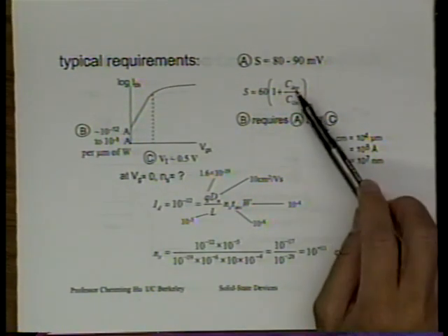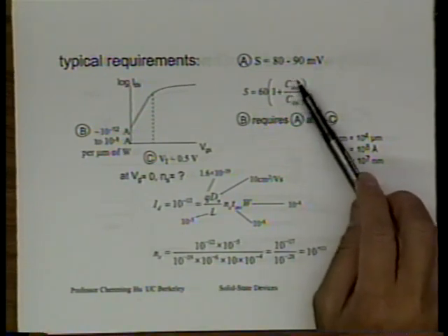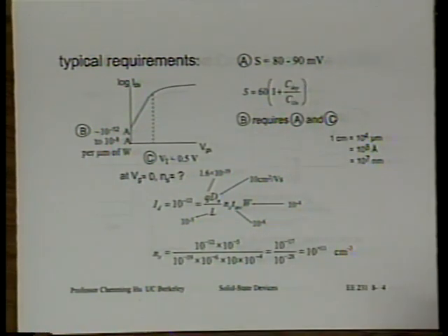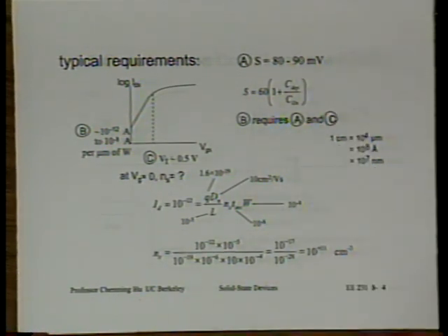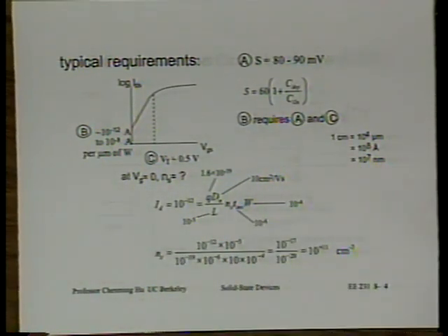The reason is we also have been reducing the depletion region thickness, WD max. One reason, which we mentioned last time, is to control the short channel effect. We have to use small WD max. So we're not really getting better swing either. So that pretty much maintained this value. So these are typical values.